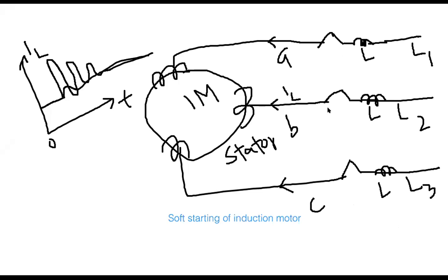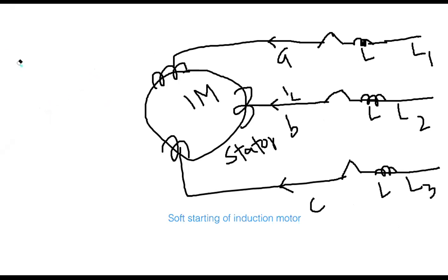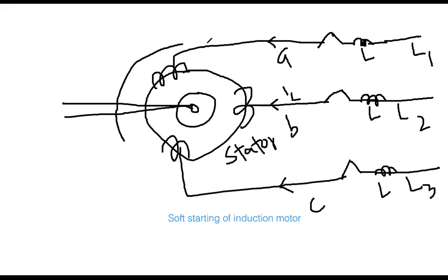Okay, say this is my structure. And let me just remove this thing and let me draw that. This is the rotor and let me draw the shaft. Okay, so for example, we energize the circuit, three-phase system, and you remember in the previous class I told you there will be a rotating magnetic field of the stator, which is phi s, which is moving by 120 f over p.